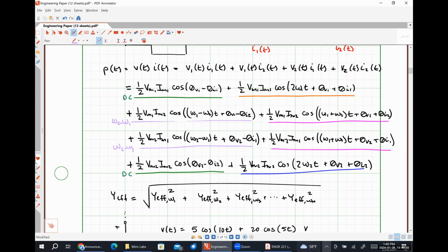So with this frequency, you will have 5 terms. Well, let me rephrase that. Assuming that omega 1 and omega 2, neither of them are 0, you will get 5 terms. If one of them is 0, you will get 3 terms. Yeah. If one of them is 0, you'll have a DC term, omega 1, and twice omega 1. But if omega 1 and omega 2 both are not equal to 0 and are not equal to each other, you're getting 5 terms. How does the circuit have?